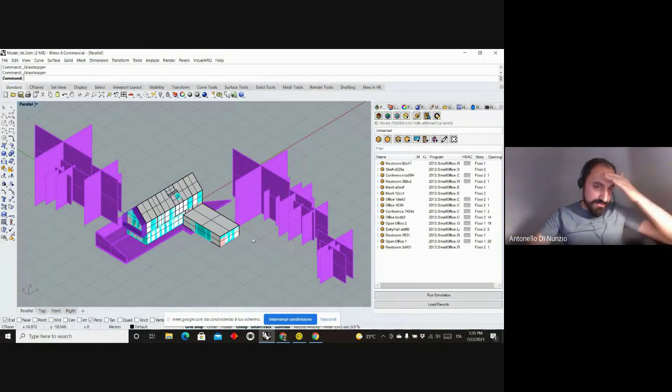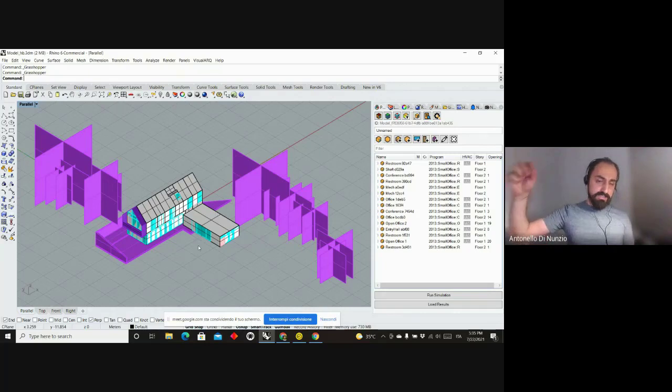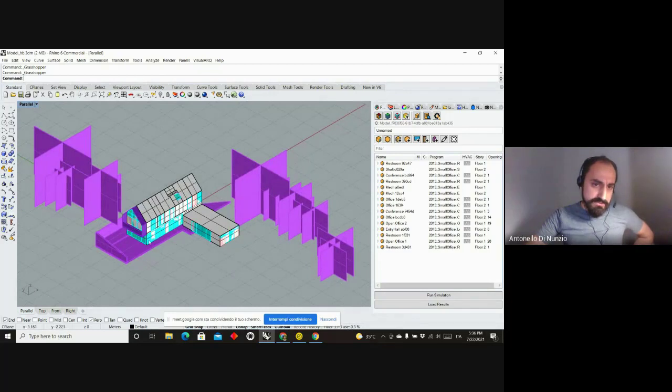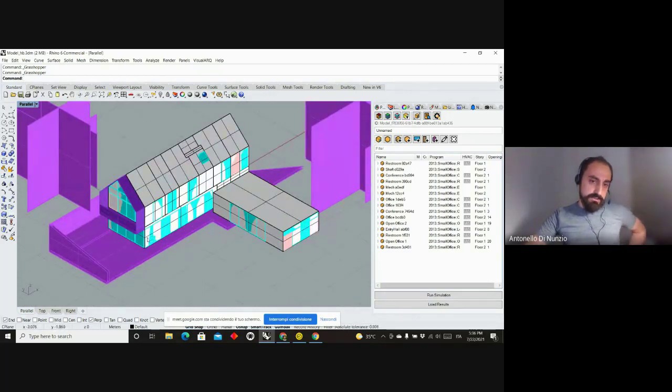Okay, yeah, one of the features that we have in Pollination Rhino is how I can take data from Rhino and move this data inside Grasshopper. Maybe, for example, you can use part of the Honeybee script to change the room. And after your changes, you can go back to Pollination Rhino with the bake functionality. So, for example, I want to add some louvers here, and I want to do it dynamically, using the louver shades component from Honeybee.